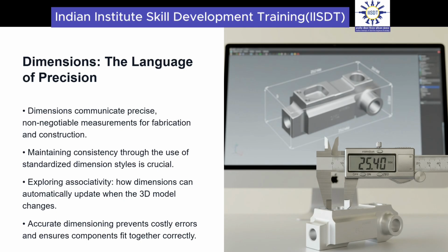But the real game changer in modern software is associativity. In older 2D CAD, if you changed the size of a part, you had to manually find and update every single dimension associated with it, a tedious and error-prone process. Today, with parametric modeling in platforms like SolidWorks or Revit, dimensions are intelligently linked to the model's geometry. If you lengthen a part by 10 mm, the corresponding dimension updates automatically. This dynamic link is a cornerstone of modern design, drastically reducing the risk of errors, saving countless hours of checking, and ensuring that the final documentation is always a perfect reflection of the model.